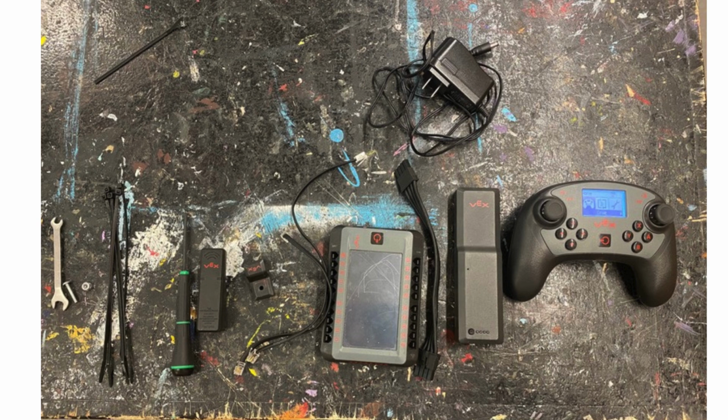Design 3 focused on using FDM printing to produce a PETG head and potentially using a TPU-based solution for the neck. Design 3 allowed for flexibility due to the varying elastic as well as rigidity properties of the plastics. Design 3 also shifted from a micro:bit-based solution to the VEX hardware solution, since the micro:bit was limited to 3 Gs. For our prototype, we used PETG to produce a head within the desired dimensions, and used a VEX IMU to capture the max Y and Z acceleration values.